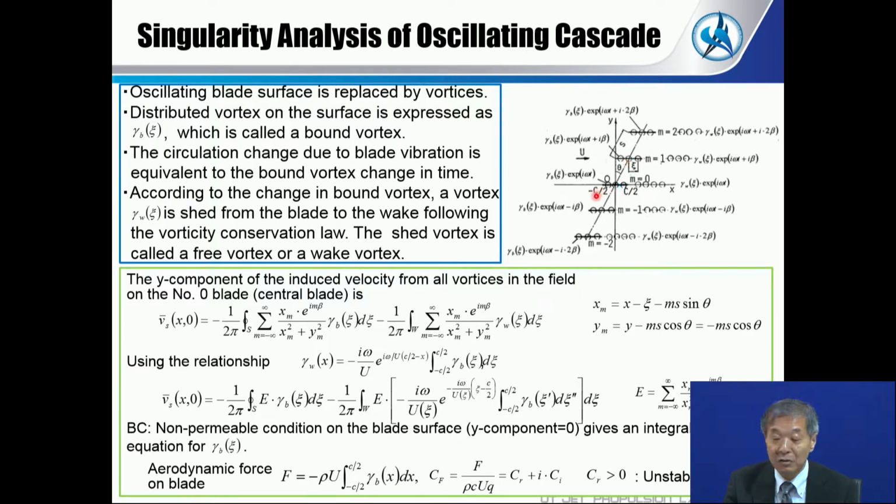Okay. And again, in this model, there is an interblade phase angle between the blades. It's a constant interblade phase angle beta. So there is the same unsteady aerodynamic phenomenon on each blade, but they have a constant interblade phase angle between each adjacent blade. So there is a wavy motion transported in the cascade direction. That is the modeling of this cascade flutter.